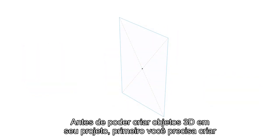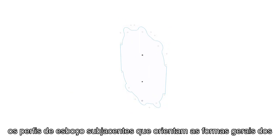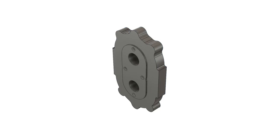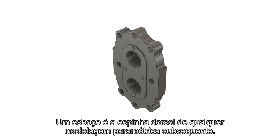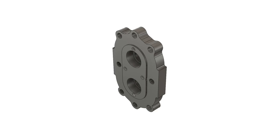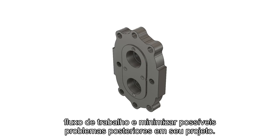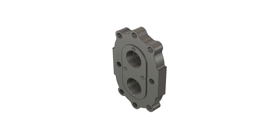Before you can create 3D objects in your design, you first need to create the underlying sketch profiles that drive the overall shapes of the parametric solid, surface, or T-spline bodies that make up your design. A sketch is the backbone of any subsequent parametric modeling. If you create a robust sketch profile, you can improve your workflow and minimize potential downstream issues in your design.